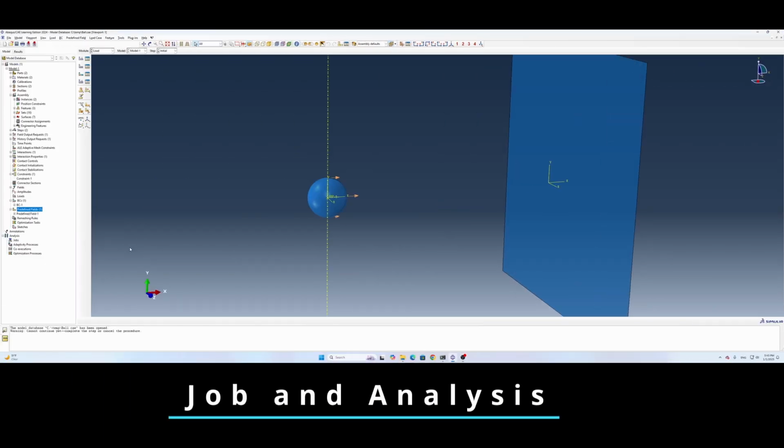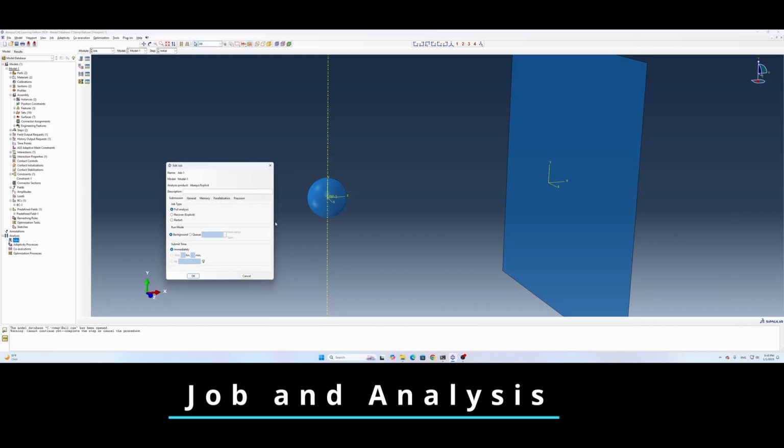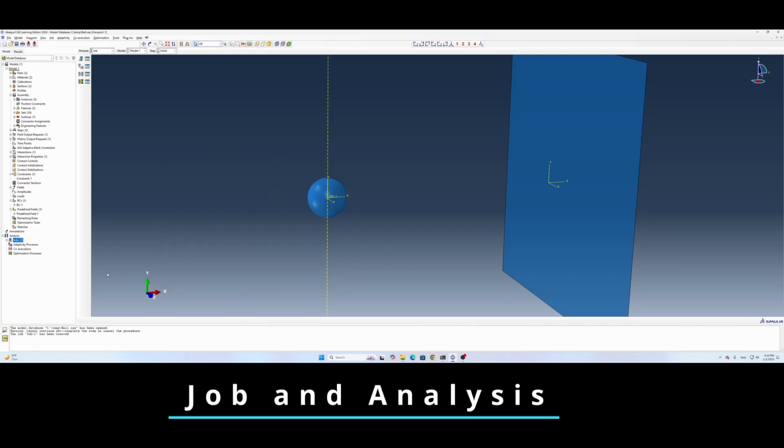Finally, we are ready to create a job for the analysis. We double click the jobs and then continue. For the precision, I always try to use the double precision because it can give me a more precise result. So hit OK. Then we can run the analysis. Right click and then submit the job. OK.